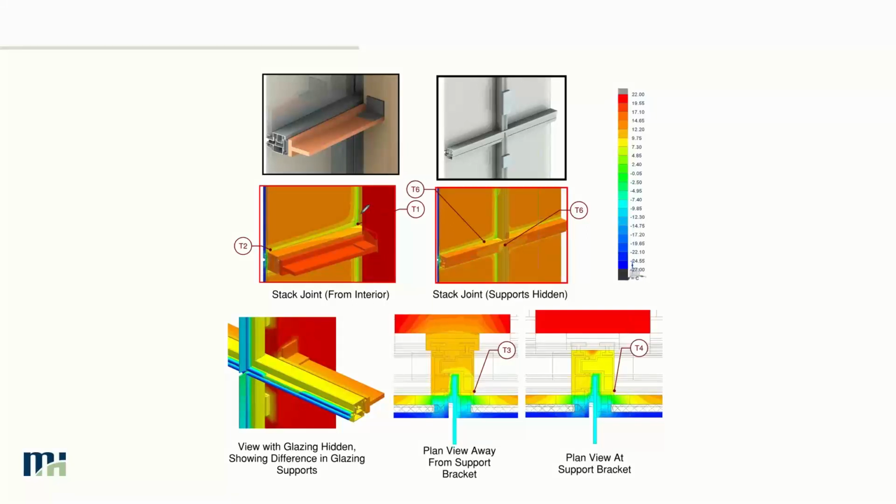And in this case, we've identified, again, the corner. We've identified the edge of glass through the field of the wall. And then looking at different points of the system of where it's located, whether it's right at this bracket or right in behind where the timber mullion is hidden, an area where interior air is harder to get to take away any kind of moisture buildup that's there.